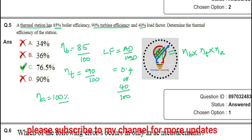Why? Because with the use of load factor we cannot find the efficiency of the alternator. Now it is equal to the efficiency of the boiler, 85 divided by 100, into the efficiency of the turbine, 90 divided by 100. We want to represent in 100, so the alternator is 100 by 100, into 100%. So 100 gets cancelled, 100 gets cancelled.